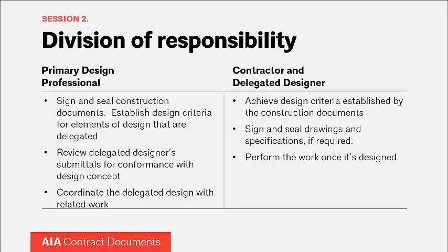design concept. One thing that primary design professionals, your architects and engineers, should be aware of is not to overstep the bounds and attempt to re-engineer or redesign something that has already been delegated. When you're going to be reviewing submittals provided by that secondary designer, usually the way it is done, and at least the way you'll see it in the AIA's contract documents, you're going to be reviewing the submittals for conformance with the design concept, right? Relatively light touch as far as reviewing the work of the other designer.